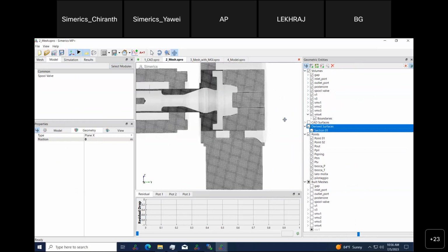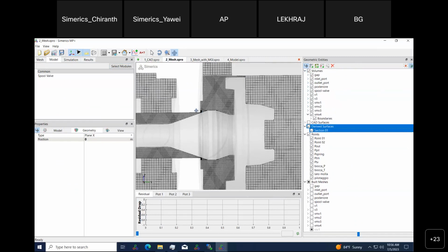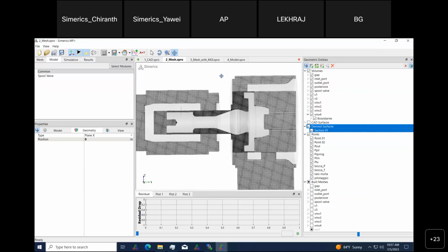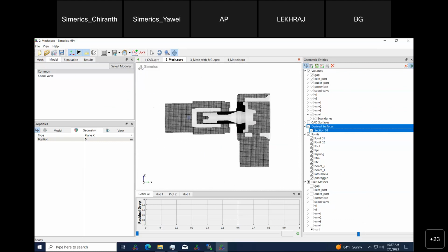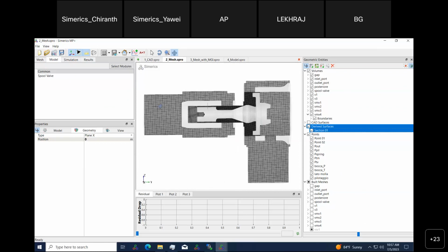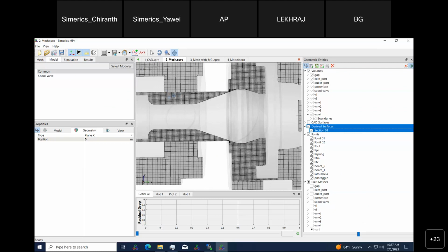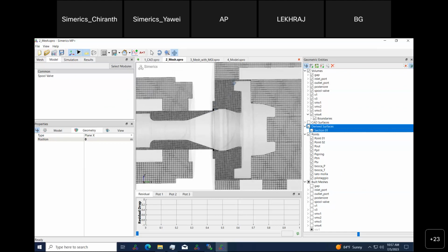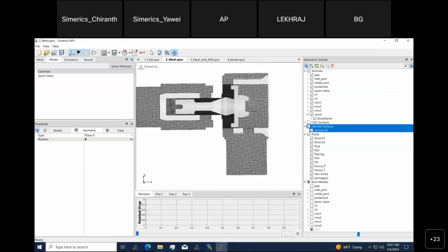And you can see near this liquid zone, I can also use a different mesh setting, a different mesh size. With all the volumes created, the next step is to build the connectivity. For example, fluid comes in from this inlet port, then enters this cavity, leads through this gap, pushes the valve open, and eventually exits at this outlet.